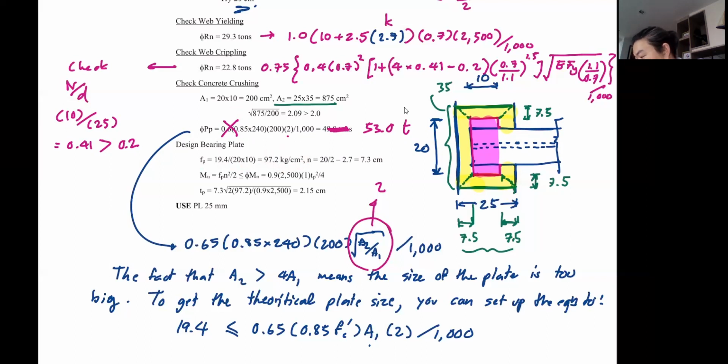And N here, because it's 20 centimeters wide, half of that is 10 and then minus K. So the cantilever length of the plate is actually 7.3 centimeters. Again, I use this formula, or you can just use this one, where you have the uniform load and the cantilever length, and it gives us the thickness that you have to choose.